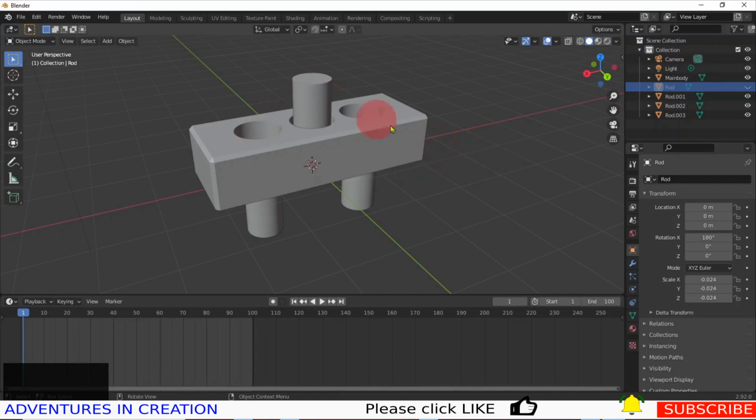I managed to duplicate it in the same place. So what I'm going to do now is tell it this is where I want this rod to start from. If I select this rod and I select this point over here, these are my keyframes. And you'll see that over here, these little keyframes come on. So that says that rod is going to be there at frame 1. So I'm going to do the same thing for this rod.